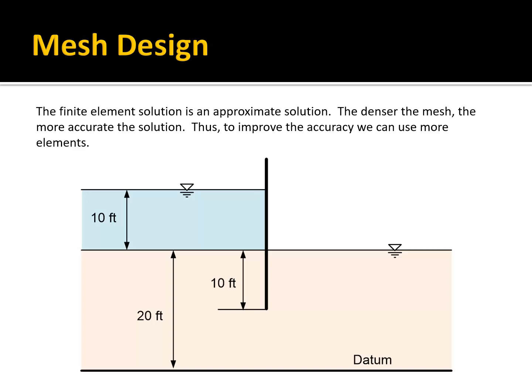Like if we were solving some sort of three-dimensional, super complicated stress or flow analysis, you'd have a lot of elements. Maybe like in groundwater problems where we have three-dimensional elements, you could get maybe 500,000 or 1 million elements. But in 2D seepage problems, I promise you will not ever get into a case where you have too many elements to solve. So let's look at our classic sheet pile problem that we've looked at before.